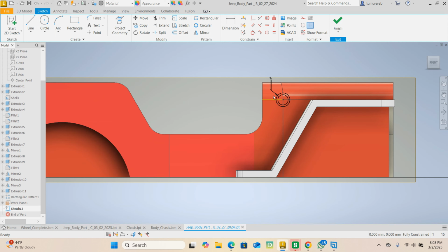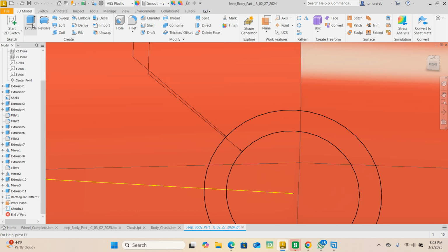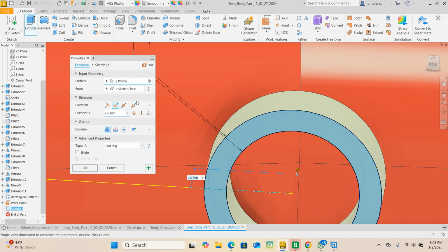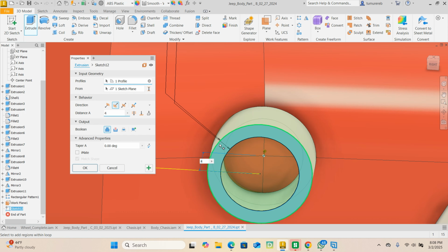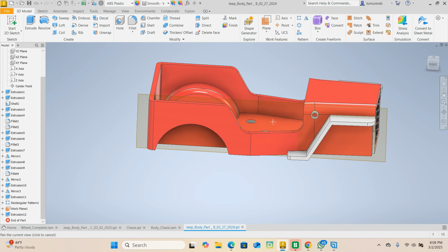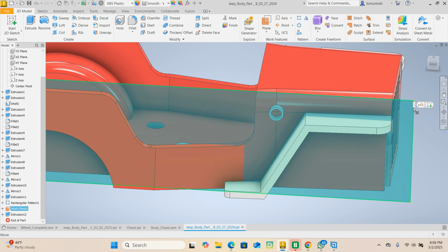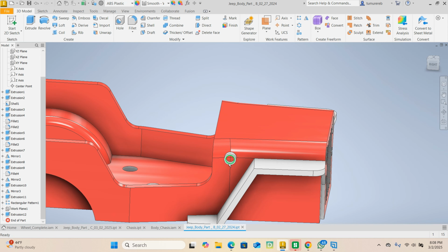And then finish sketch, extrude. Extrude how much? We want to flip, a distance of 4, and Inventor is so smart. It already knows that this must be joined. I love it. I love Inventor. Inventor, you and I are in love. Alright. Okay, that part is done.